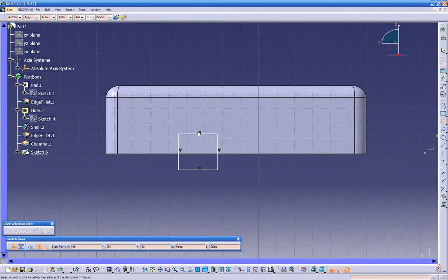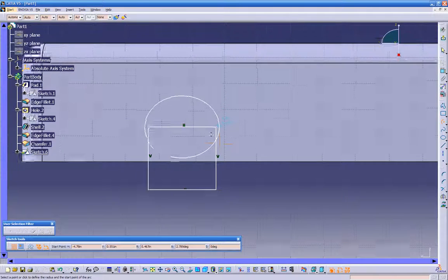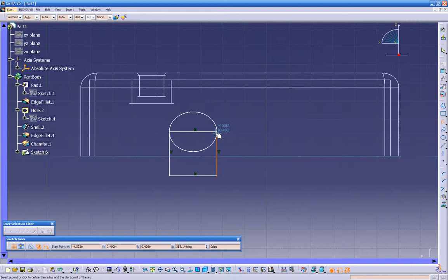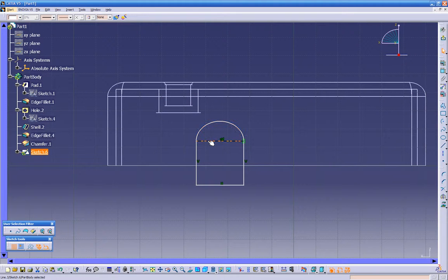So let's click the middle point to this endpoint, and you can see how it snaps into point. We get that full moon. And if it's hard to see, we can come down here and do a wireframe, and see how it gives the full moon. That way we know that we're in the endpoint of that line, endpoint of this line. We get the full moon again, click OK. And let's create this line as a construction element.